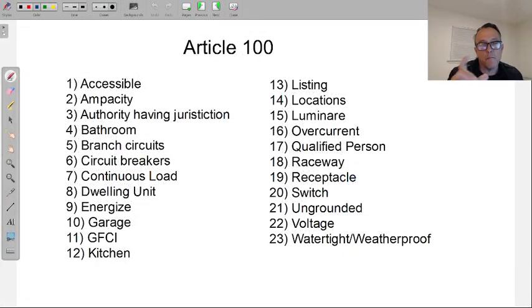So inverse time breakers, and you'll see different numbers here depending on what book you're looking at. Some say 5, some say 8 seconds. But that's about the delay. 5 to 8 seconds. These breakers are designed to hold off on opening the circuit in the event that amperage has gone past what their rating is. They give it about 5 to 8 seconds for things to temper down after they've started and after they've energized.